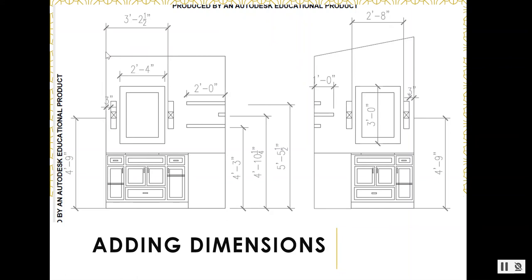Here, they're showing another 3 feet 2 inches, and that's where they would place that sconce. But it's the same height. They're even. Here's showing the mirror in between. And so here we have all the dimensions that we need to hang all of these items for the contractor.